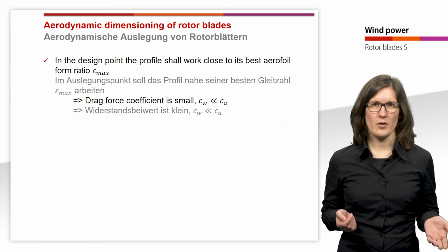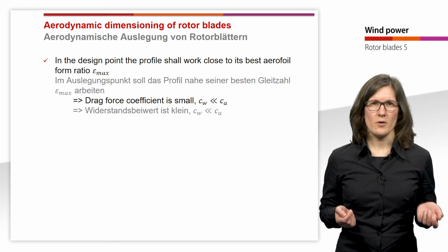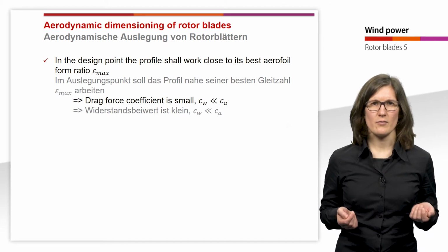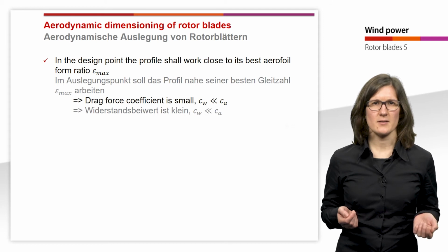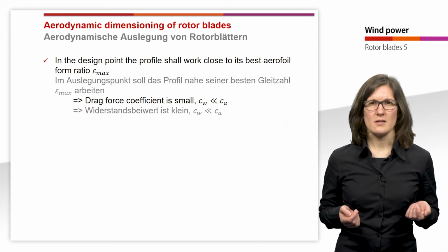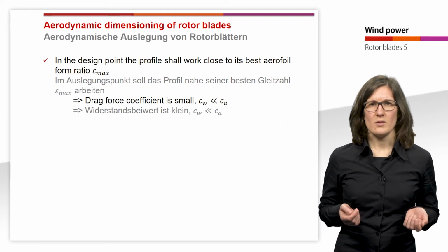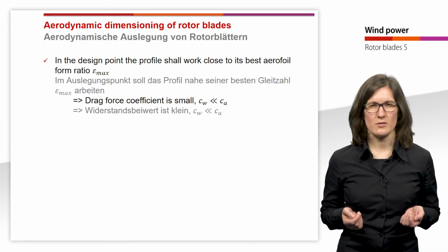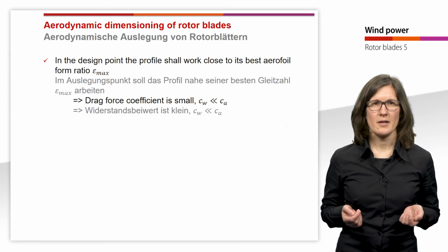And in the design point, the profile shall work close to its best aerofoil form ratio, epsilon max. And this means that the drag force coefficient, Cw, is very small compared to the lift force coefficient, Ca.